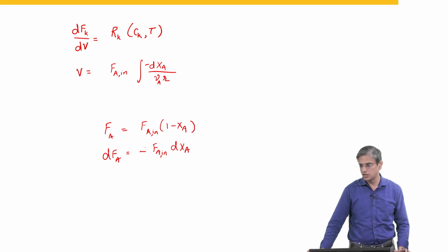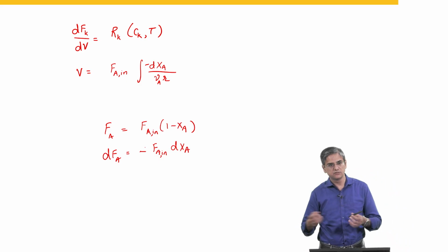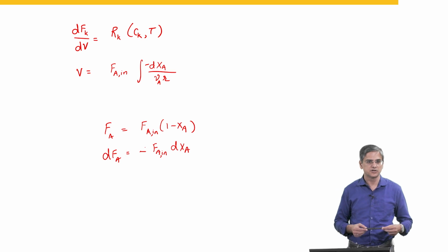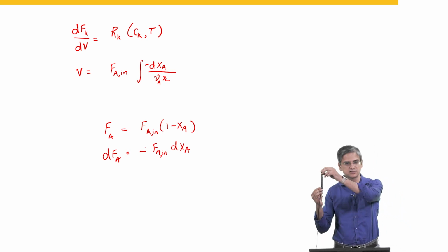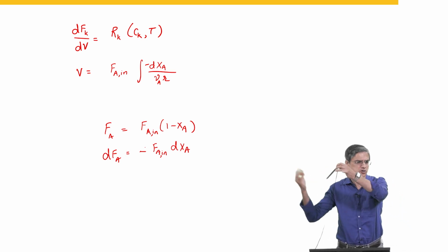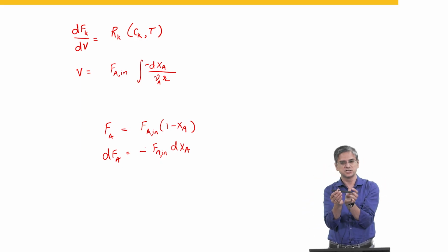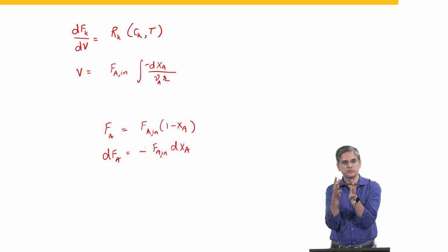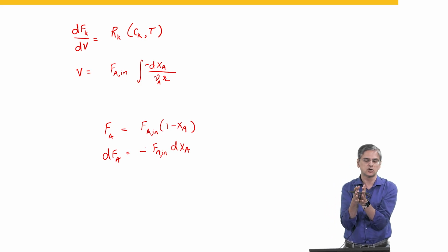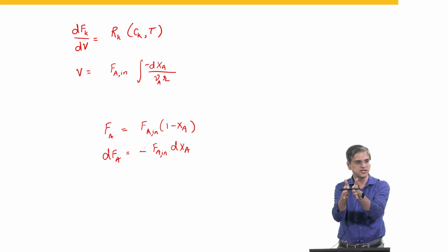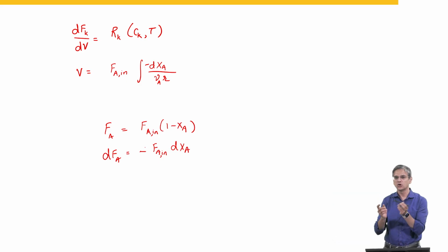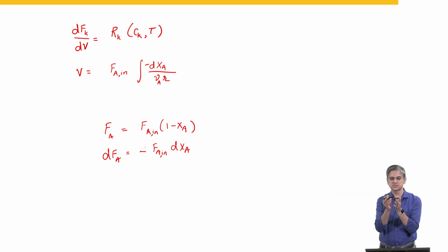Okay. So, for example, when we start our reactions in our lab, let us say this is the tubular reactor that we are going to use in the lab, right. Assume that this is the tube that we are using, we do gas phase, solid catalyzed gas phase reaction. So, we will fill, you guys want a lab tour? Okay. So, how we start the reactor is, we will put the catalyst in the reactor.